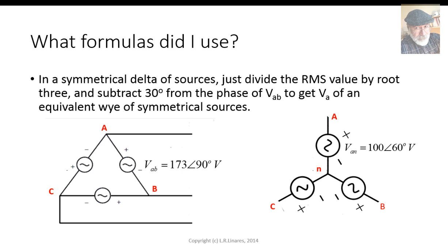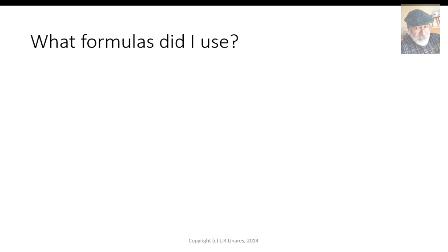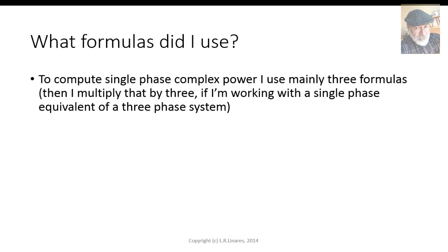Now we know how to convert deltas of impedances and deltas of sources to equivalent y's. What other formulas do I use? Well, the ones for power. You see, to compute single-phase power, I mainly use 3 formulas. And if I am solving the single-phase equivalent of a three-phase system, I have to remember to multiply that times 3, because after all, the single-phase equivalent is only 1/3 of the power system. Well, let's begin. 3 different cases.